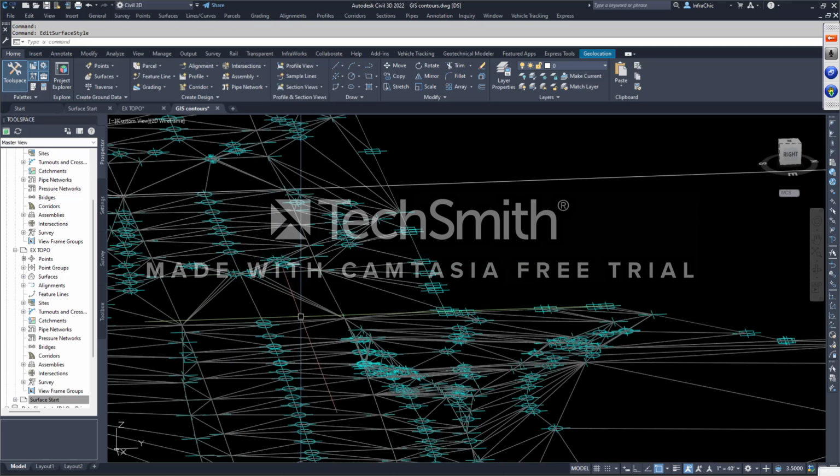So again, this may be made from actual points, or it may be made a different way. You can make surfaces multiple different ways, okay? When you make a surface in your tool space on the Prospector tab at the top, the bolded file is the current active drawing that you might be in, any one of these. If you expand the surfaces collection, you'll see the surface name under it, okay? I can get to the surface 5 different ways.